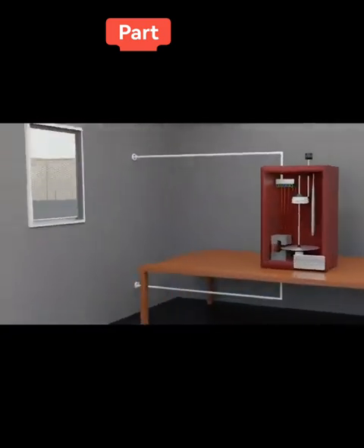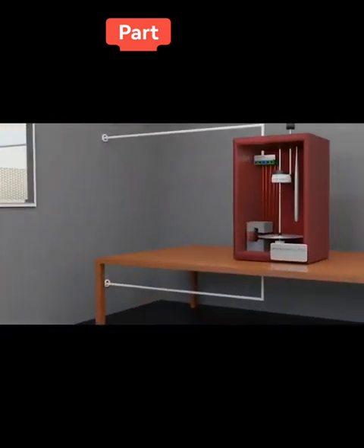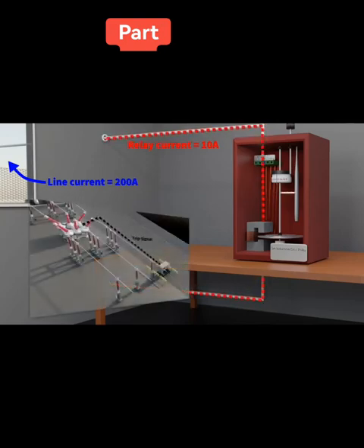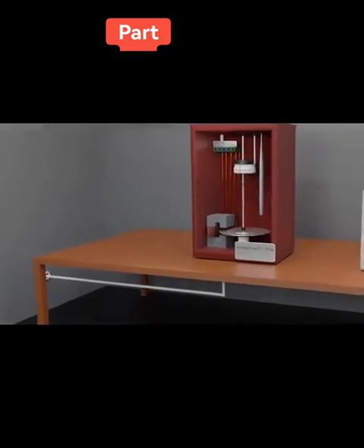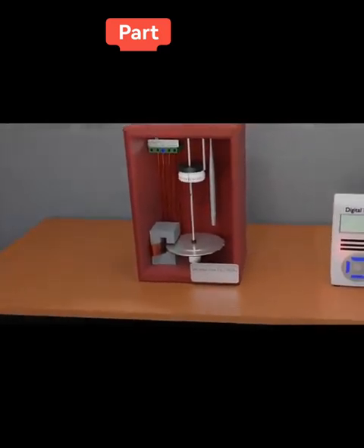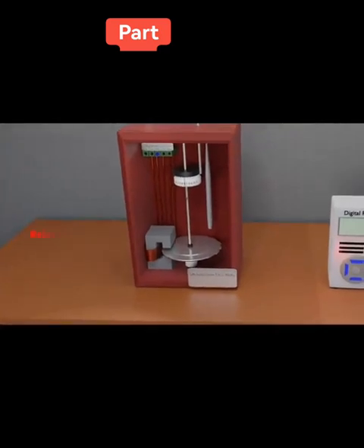So now the current through the relay has generated a magnetic field, which induces a torque in an induction disk. So it has got a disk. The induction disk therefore rotates, and if it rotates far enough, a rotating arm hits the contact, and this initiates the instruction to the breaker.